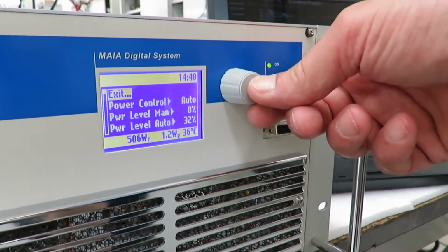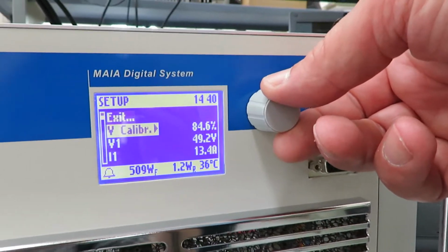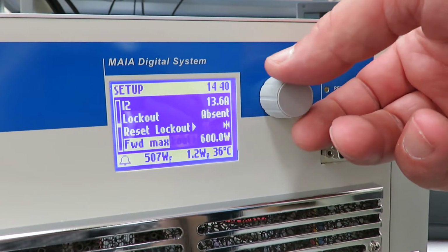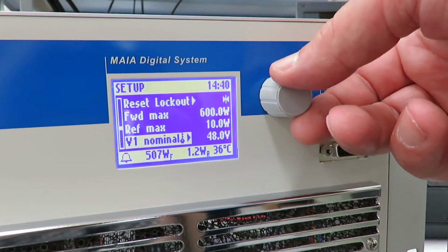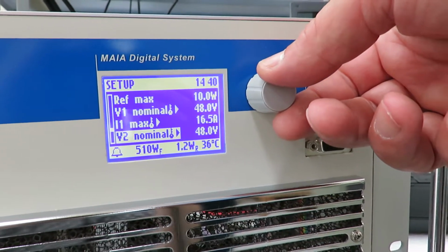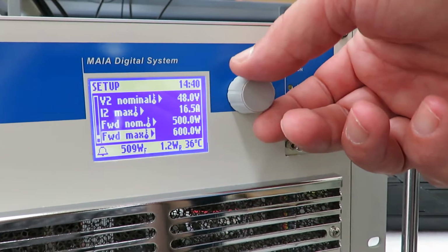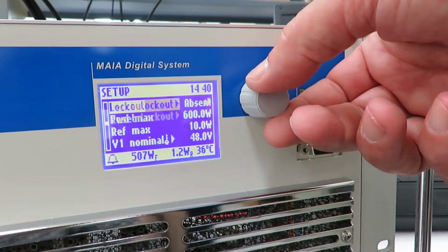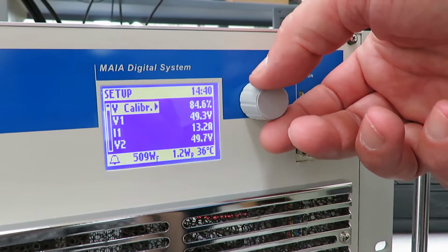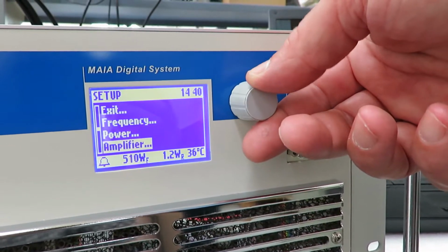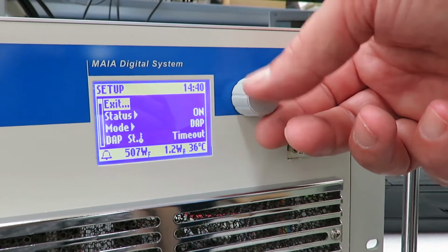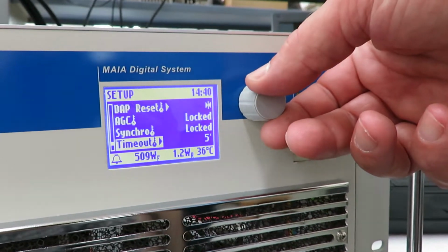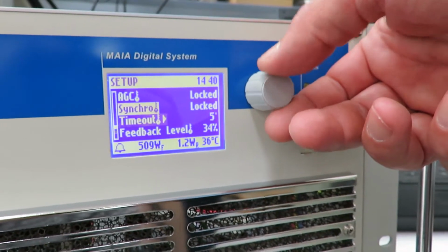The main menu gives access to sub-menus which take care of modulation parameters, RF output parameters, input parameters, control parameters, and then there are the alarm and log sections, which in real time show the user if there are any failures or if in the past some failures took place, and in any case you can have access to the log of the events, the alarms.